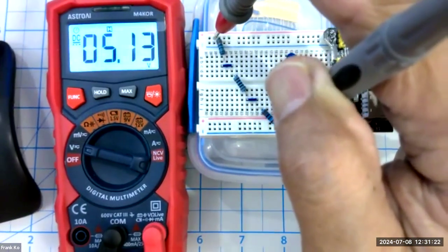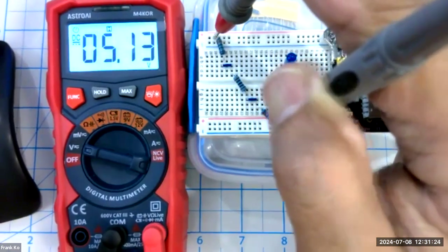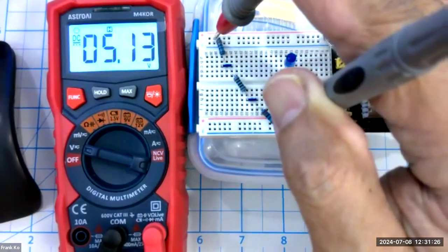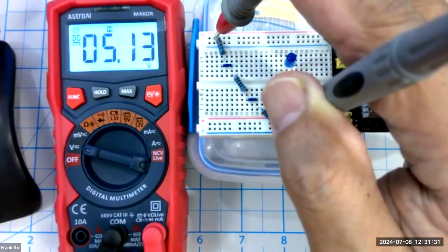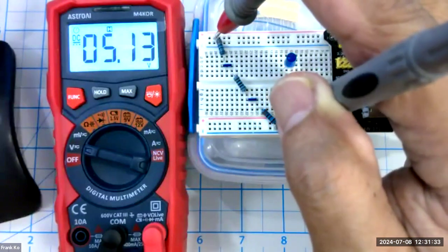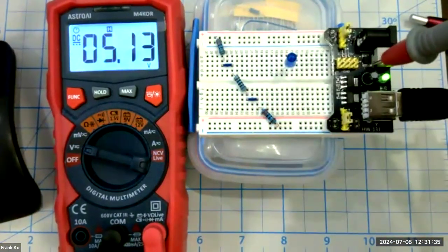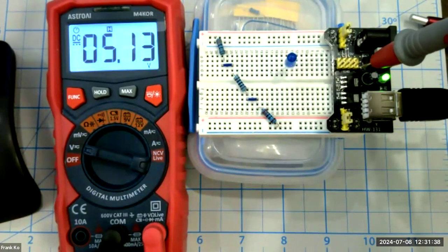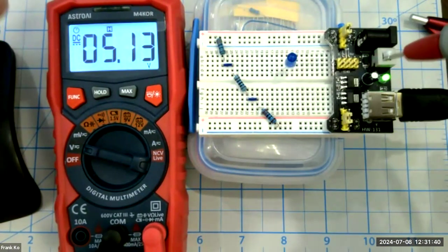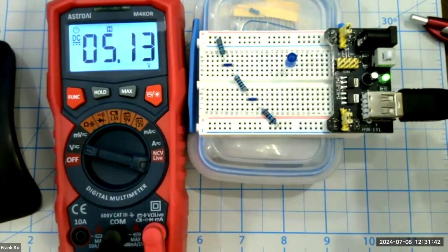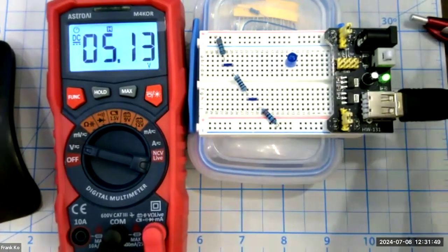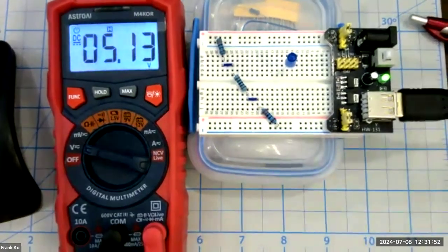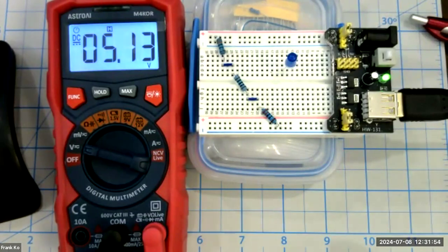So don't sweat the little micro numbers, the 100th of a decimal place for voltages. Are we close to the board's output of 5 volts? Yeah, we're pretty close, and we're happy with this because this board happens to put out a little bit more than 5 volts. Some of these boards will put out a voltage like mine at 5.13. If yours puts out 5.02, great. If yours puts out 4.97, that's okay also. There's a margin of error. As long as it's close to 5 volts, we are dancing the happy dance.